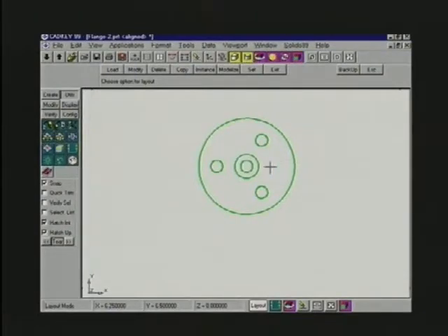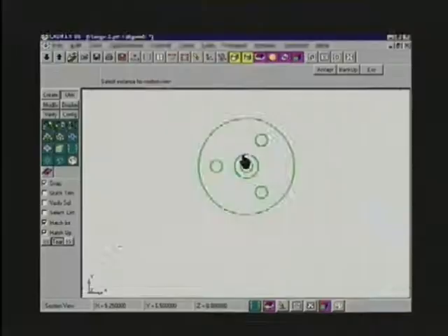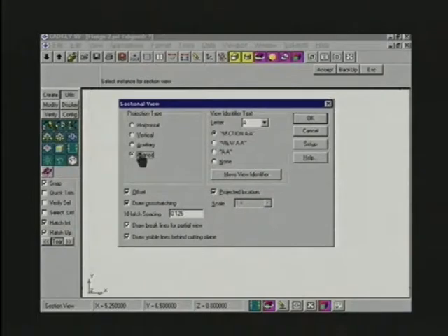Now this time I want to cut part way through. I want to show both of these holes without cutting straight through and without throwing an offset in. I'm going to do the aligned section. So I'll pick my little cutting tool and choose the aligned section, but turn off the offset, because I could do an offset aligned section, too complicated for this part.